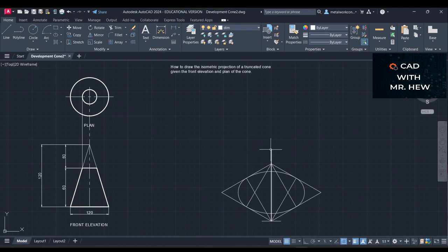So at this point, which is the height, we're gonna draw another isometric square up there of size 120 millimeters. All right. So we go line. Yes, it would be 120, and the angle would be right. Then we're gonna come around again, and the line will be 120.